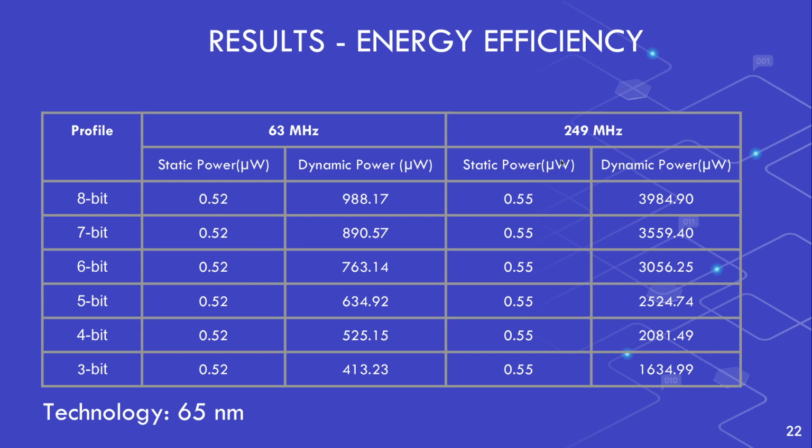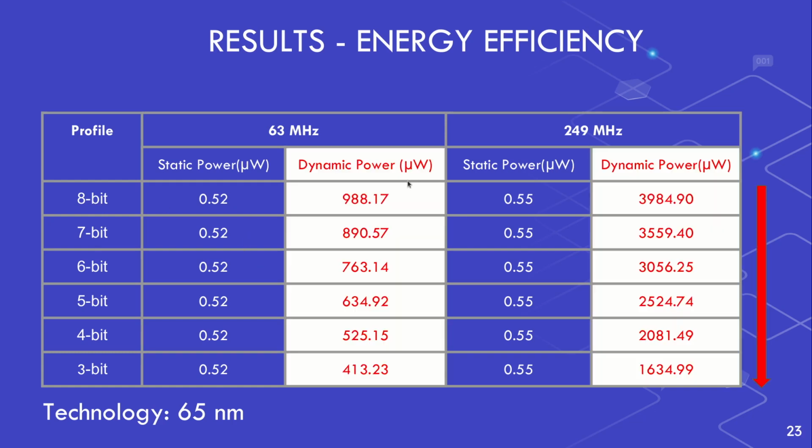So when we observe the power results here, we have these profiles. Here we have one architecture, and this configurable architecture can perform different approximate profiles and the precise one. And here we can conclude that the dynamic power is dominant over the static one. We can also conclude that the clock gating logic is important to reduce the dynamic power, since it is dominant for this case study.